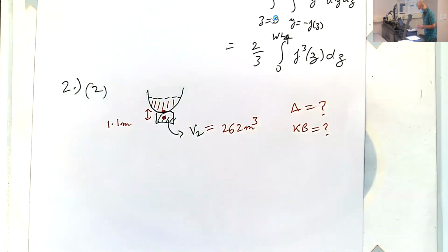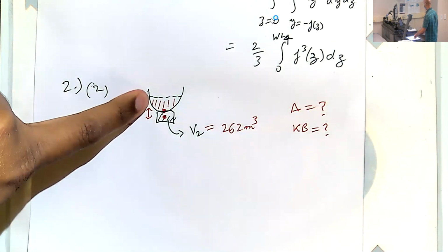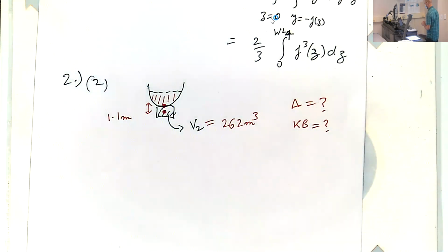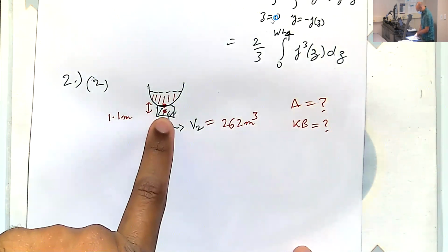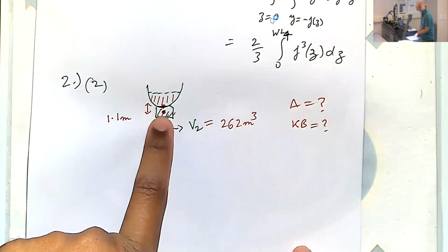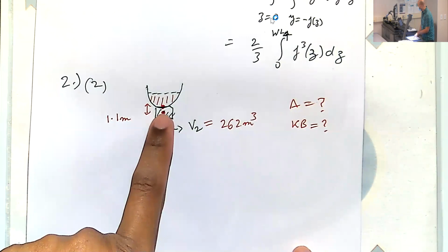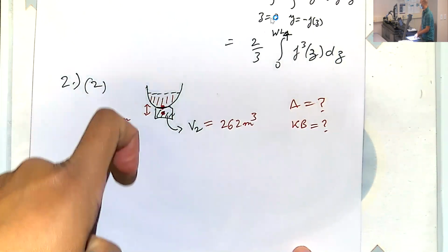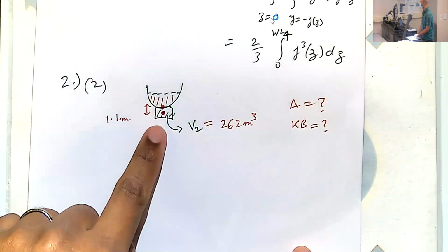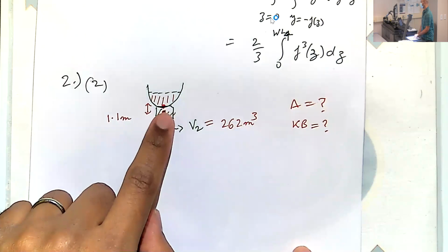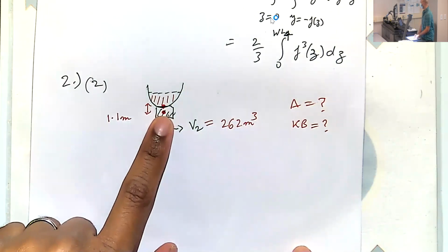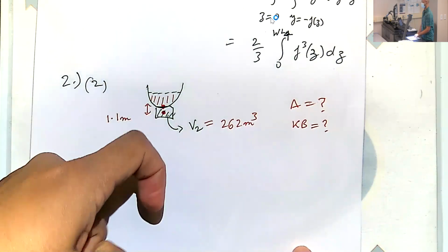I should have told you that the submerged volume of the hull doesn't change. I think I missed that in the question. So it depends on the density of the additional object, whether your hull will sink further or rise up in the water. If it's a block of wood, you'll rise up a bit because it provides extra buoyancy. If it's a block of steel, your hull will sink further down.